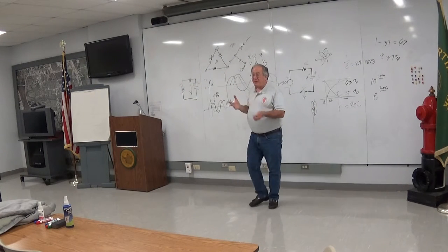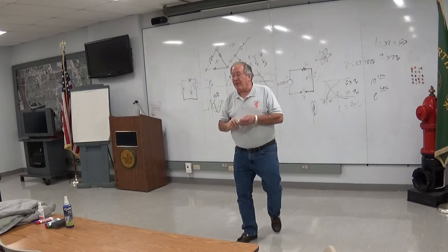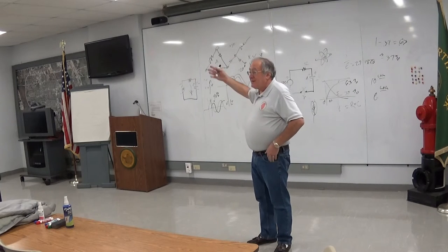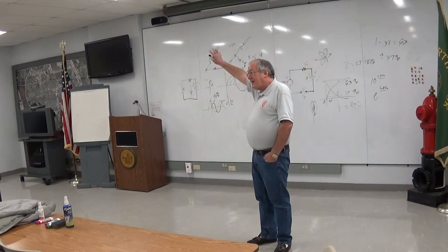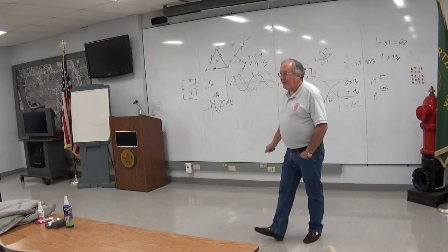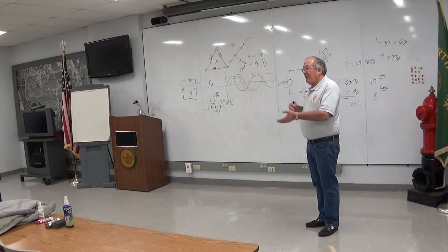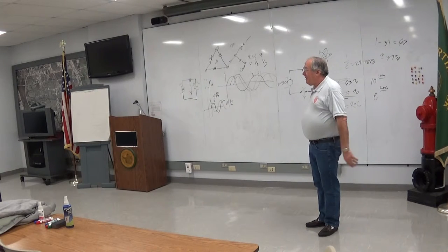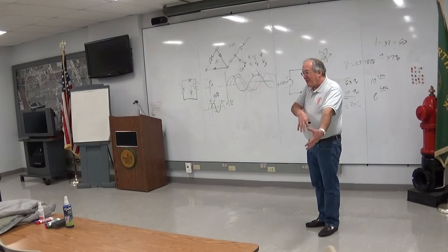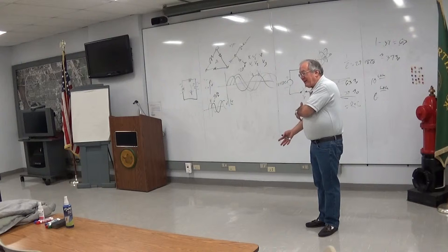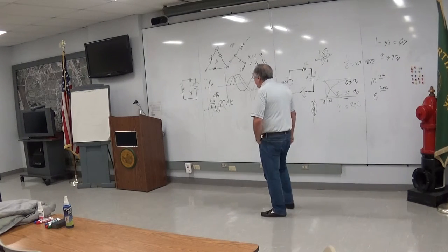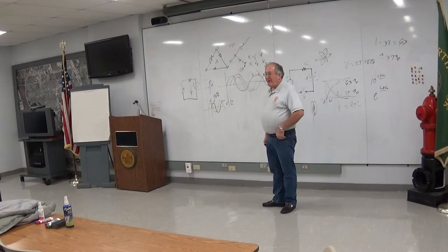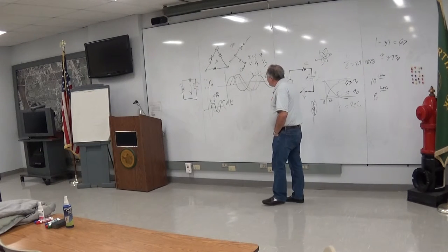And you can actually translate one into the other. And the reason things are usually sent using delta winding on these long transmission lines is because they don't have a neutral return. But at some point they need one. So they have a transformer that has a delta winding on the primary and a Y winding on the secondary, and they kind of convert it over from one to the other. The transformer actually has 3 separate windings in it for each phase.